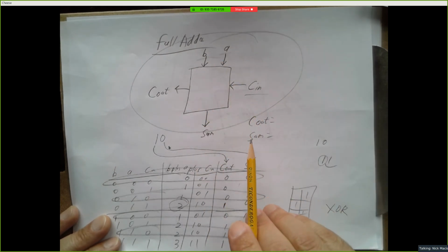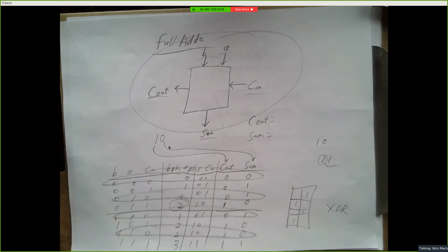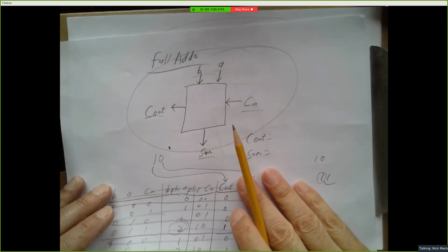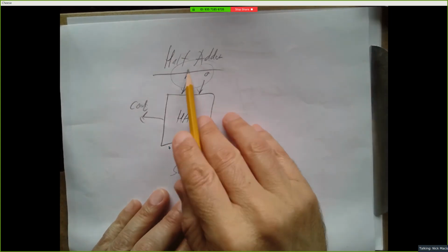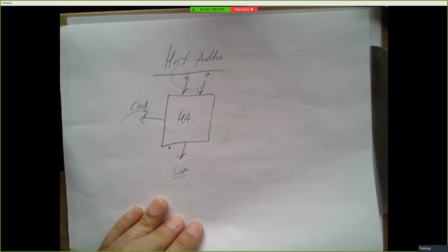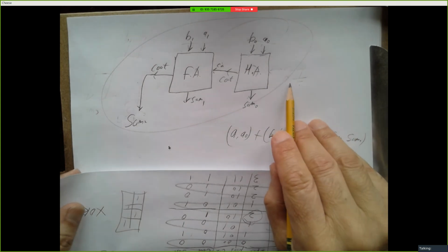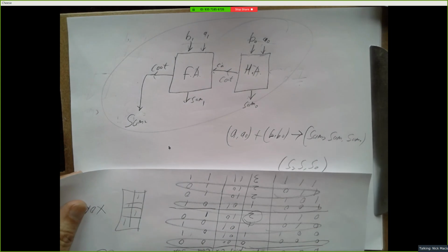But the full adder always looks like this, right? 2 bits and an incoming carry, and then an outgoing carry and a sum. Would it ever switch from a 3 to 2 device? No, not for a full adder. There are different versions of this for matters of efficiency and such, where we might have other devices with extra inputs or extra outputs, but a full adder is always 3 in, 2 out. You can put them together as many as you want to add larger numbers of whatever size you need. That's the building block. For a half adder, it's 2 in and 2 out. You can fake a half adder by taking a full adder and tying that extra input to ground, but if you just design a half adder, it takes a lot less circuitry.